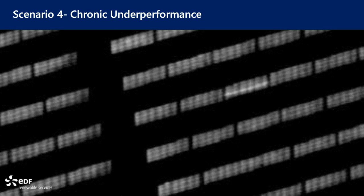So what you see here, if you look just to the center of the screen, is a line that is a little bit brighter than the others around it, right? So what does that mean? Well, essentially when a module is exporting power, then it's going to be cooler than those around it. So if you have a string of 6 modules, you'll see 6 individual dots, because those are not making power, so they're hotter than those around them.